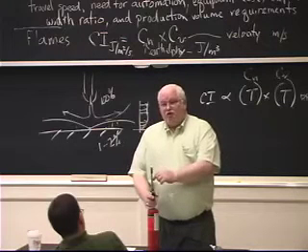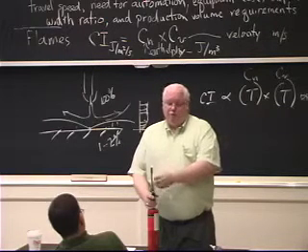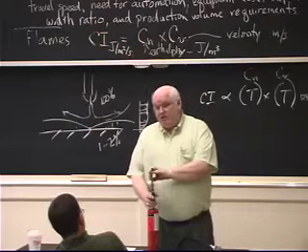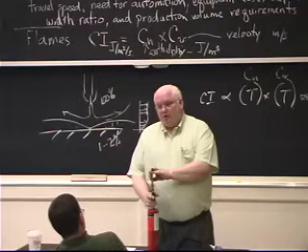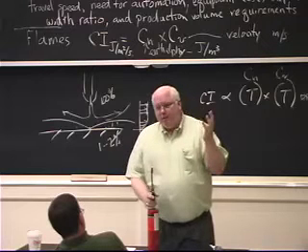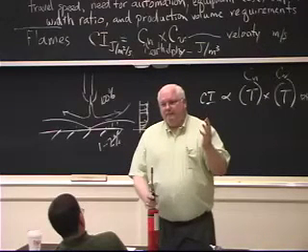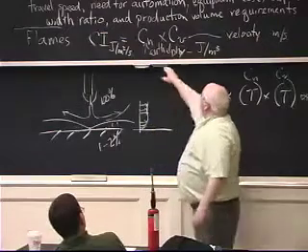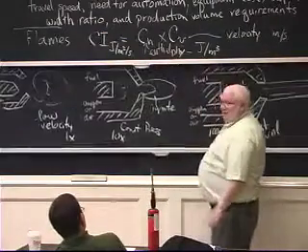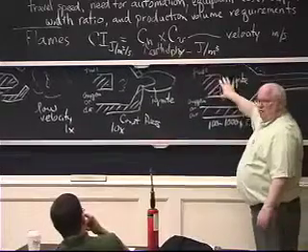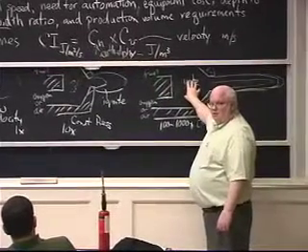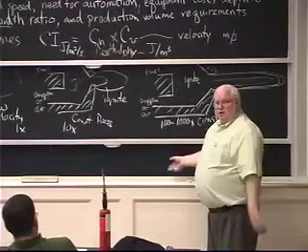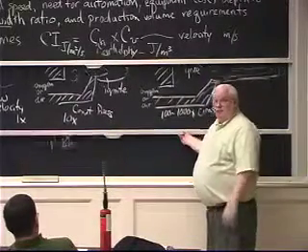Right, if it goes back down, you get a jet burner, and momentarily you hear a pop. If I could sustain the ignition, but it's not easy to sustain the ignition in a jet burner. Usually they blow themselves out, they flame out. You have to design a jet burner fairly carefully so that you can sustain ignition and it doesn't blow itself out. You have to have the fuel and air coming in at just the right balance and just the right nozzle design in order to run it continuously. Otherwise, it likes to blow itself out.